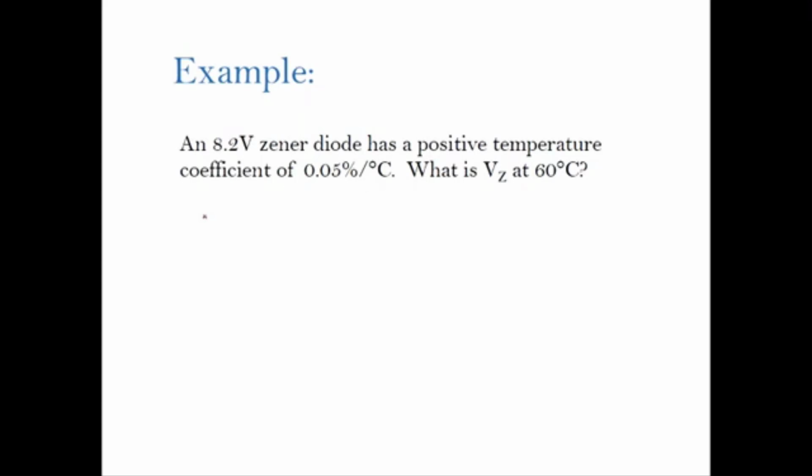So the Vz of reference, let's say reference here is 8.2 volt. Usually this is the measured Zener voltage at 25 degrees Celsius.